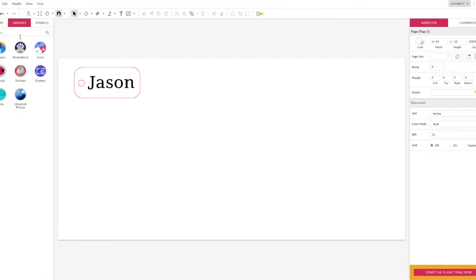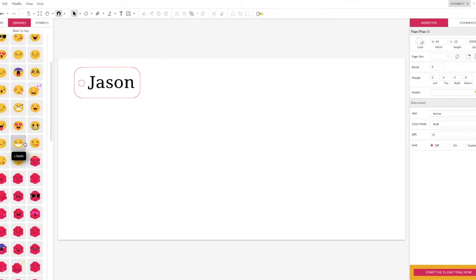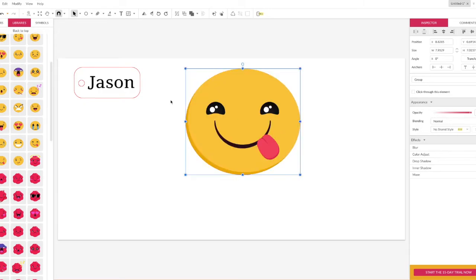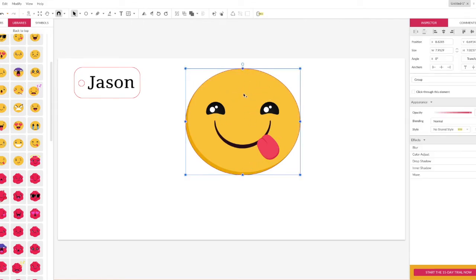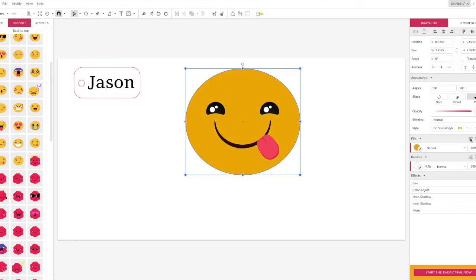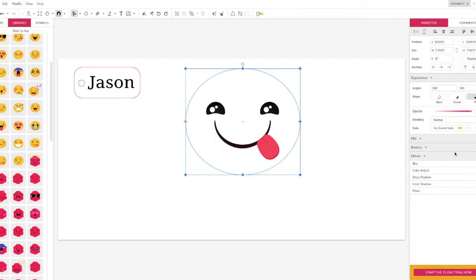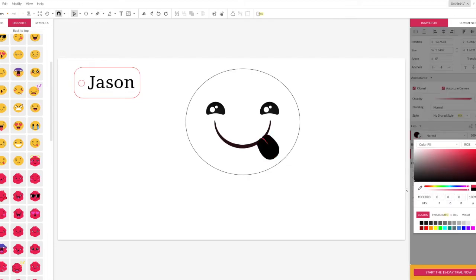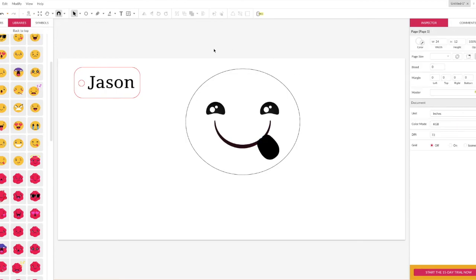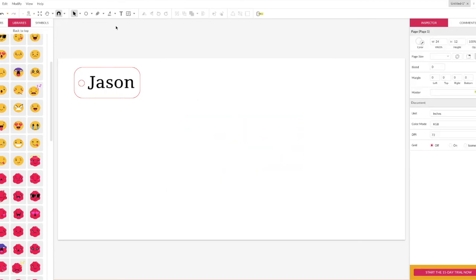Now in the libraries there are a lot of different images and things you can pull from, which are kind of fun to play with. But as I mentioned, you can only pick one of the 3 colors: black fills, red borders, or blue borders. So something like this would not be readable by the laser. You could click on this and edit this image so it only had the features that you want. So for example, I could get rid of the initial designs and change all of this so that it's black, which of course changes the image, but would allow this design to be interpreted by the laser.